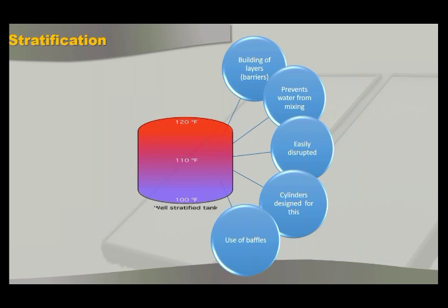I've been called out to geysers where the guy says to me, this geyser is working perfectly. It has been working perfectly for 5 years. All of a sudden, we have one shower and it's done. And all it is is a little plastic baffle. You replace the baffle and job done. So it's easily disrupted, and it has a huge effect on the efficiency and effectiveness of the cylinder. So geysers are designed with this in mind. Obviously, they've all got baffles of some shape or description.